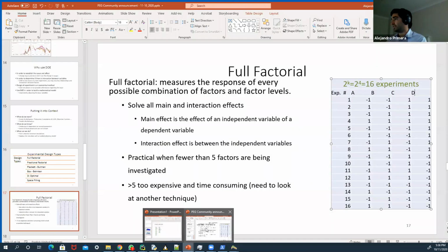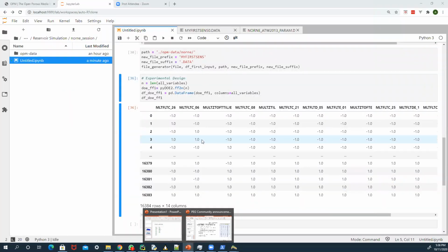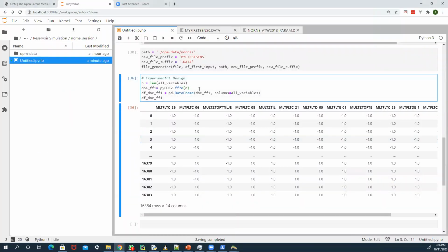Alejandro, excuse me, a question. In this case, are all the cases run in series, or is there a kind of parallel simulation you can have here? You can run in parallel, and you can generate a batch file. In the batch file, you can have a routine in Python, or an LSF queue manager, that picks wisely how many simulations to run. If you have a cluster available, you can run a lot of those cases in parallel.